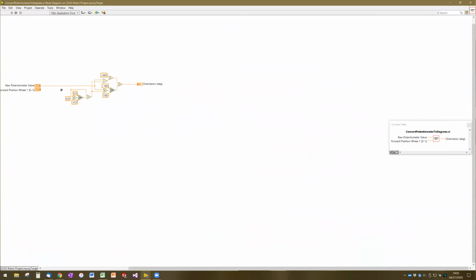So there's a check to see which side of the calibration point you're on, right? If you're on the left side, you're using the first piecewise function. And if you're on the right side, you're using the second piecewise function. And the rest of it is just the equation for the line and setting the slope and the y-intercepts, essentially. And so all this is an implementation of the piecewise linear functions that we just drew.